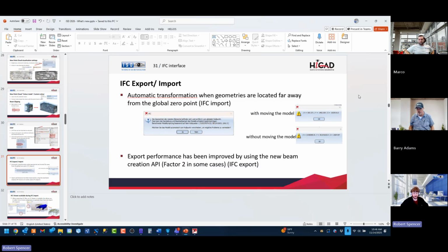It has uses, but with the IFC, you can save a Revit RVT file as an IFC and then share that with whomever. Right now, that's the only way we can view a Revit model, by saving it as IFC.